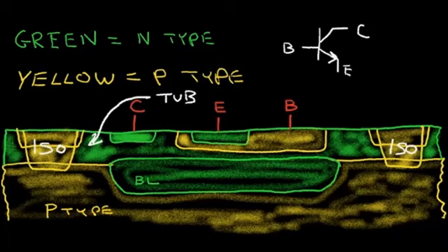Now, there will be another tub region over here, and perhaps resistors will be in this tub region. And over on the other side of this isolation, there's another tub over here that extends to the right. For example, there could be perhaps a PNP transistor in that tub. So this isolation region allows us to create different devices and have those devices isolated from each other.